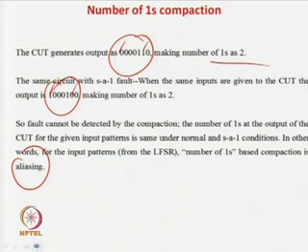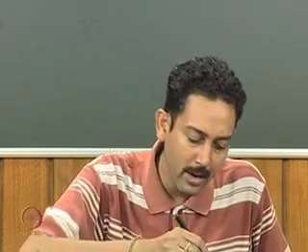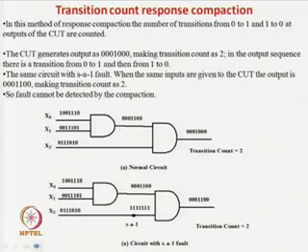So, you can select the aliasing and compaction technique accordingly, and find out what the required coverage is and which are the most important faults you want to target. In that way you can get a smaller ROM size, as well as a good coverage for the important faults, or the faults which tend to develop when the circuit is in operation, right.